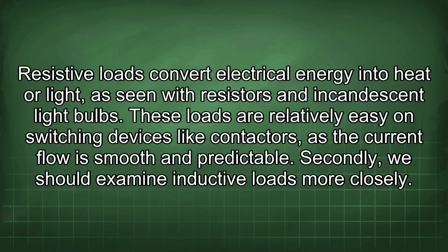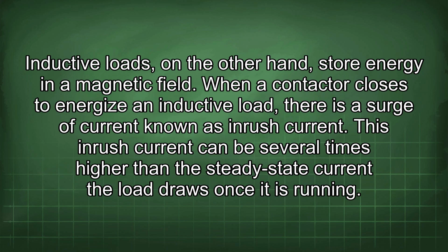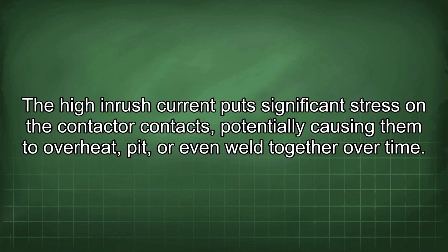Secondly, we should examine inductive loads more closely. Inductive loads, on the other hand, store energy in a magnetic field. When a contactor closes to energize an inductive load, there is a surge of current known as inrush current. This inrush current can be several times higher than the steady-state current the load draws once it is running. The high inrush current puts significant stress on the contactor contacts, potentially causing them to overheat, pit, or even weld together over time.